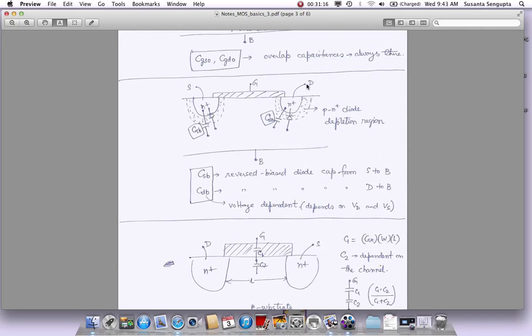If there is a voltage swing, this is actually a nonlinear capacitor, right? Any voltage swing across a reverse bias diode could cause the capacitance to change significantly, and this becomes a big killer for circuitry where a nonlinear capacitor causes nonlinearity at the output. What kind of circuits? Power amplifiers and other amplifiers, where they have a large voltage swing at the output.